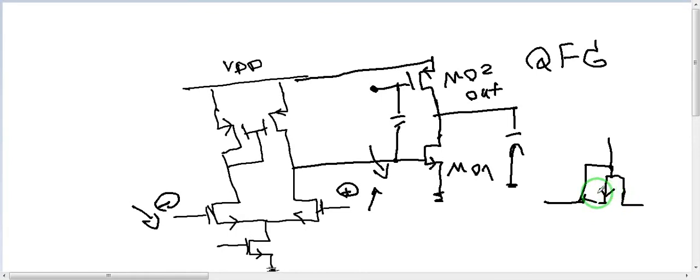So instead of a resistor, you are going to use a pseudo kind of resistor, a big resistor that does nothing, and it is better to use PMOS because of some reasons. So I'm going to add a PMOS. So this is a PMOS, and then you have the bias over here, and you are going to connect the gate source of the transistor to be in a cutoff region and act as a very large resistor.